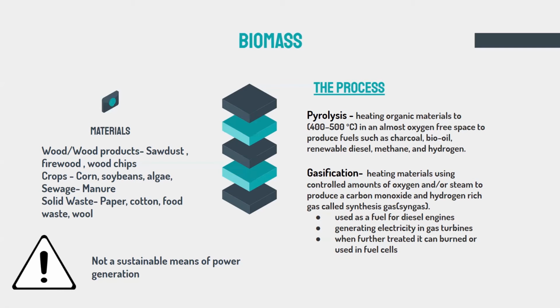So we also have gasification. Gasification is when we heat materials using controlled amounts of oxygen and/or steam to produce a carbon monoxide and hydrogen-rich gas called syngas. This is used as fuel for diesel engines, for generating electricity in gas turbines, as well as, when further treated, it can be burned within fuel cells. So this is by no means a method for us to pursue in the future.